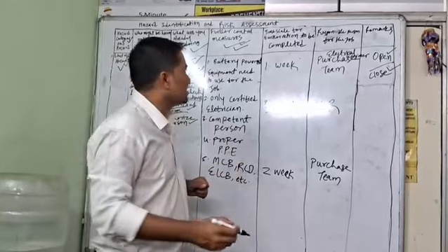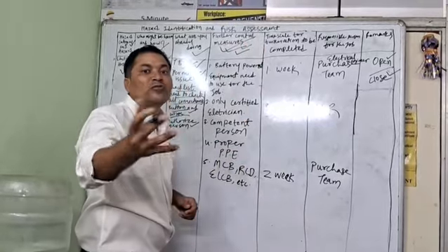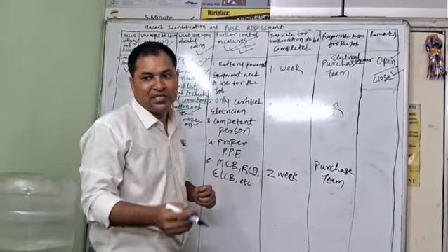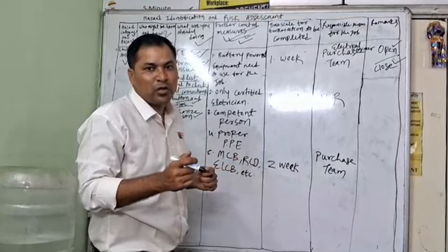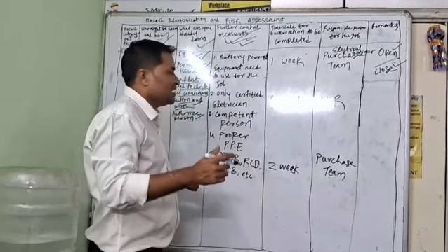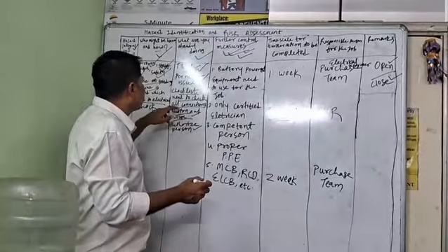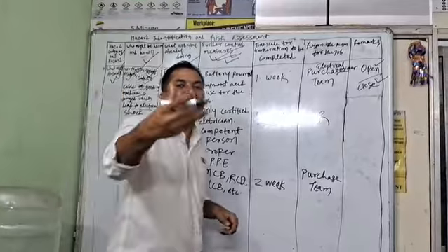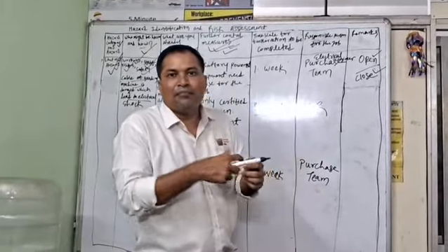So in further actions, you have to go with the control measures. What are the control measures you need to apply at the same place while working? Still the workers get affected with electrical shock and injured as well. So what you need to do here, we discussed the cable connection damage. So we'll go with the powered equipment. We'll simply go with battery powered machineries.